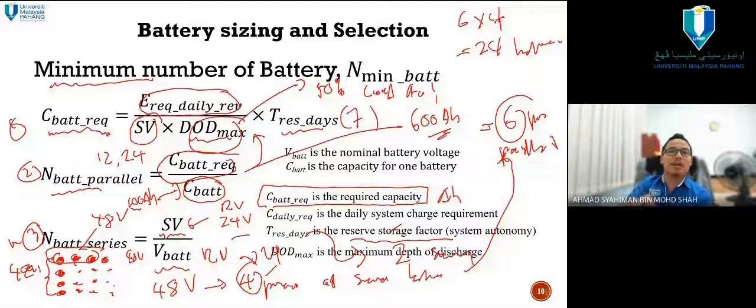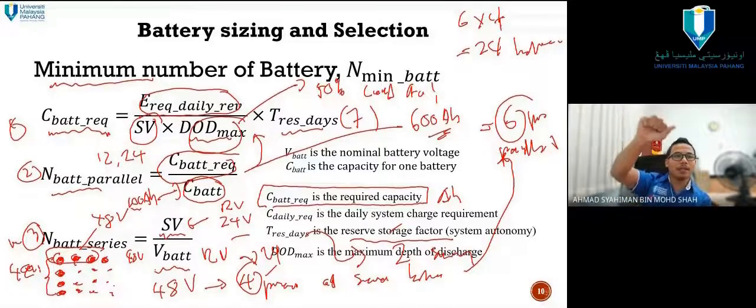So this is where all your money will go. Here is the battery budget. The panels earlier may not be much. You buy the 500 watt ones, buying 4 pieces is only a few thousand. For example, I got 700. 7 times 4 is 2,800. You're going to get 4 pieces of 500 watt solar modules, which gives you 2 kilowatts of generated power.